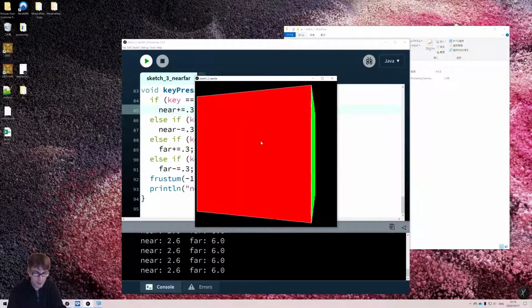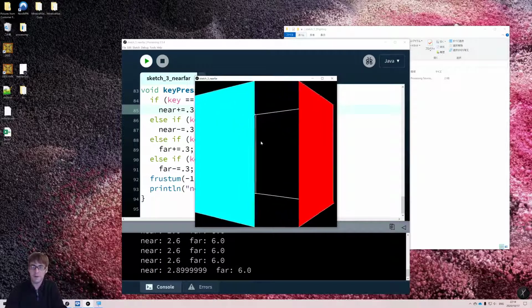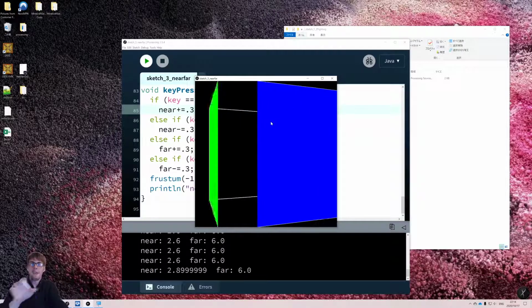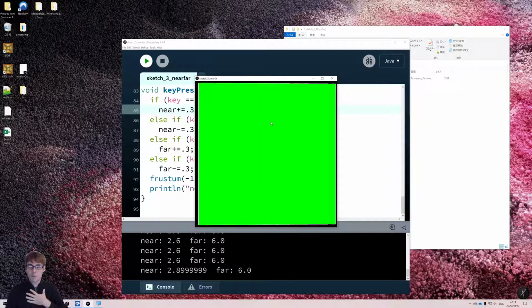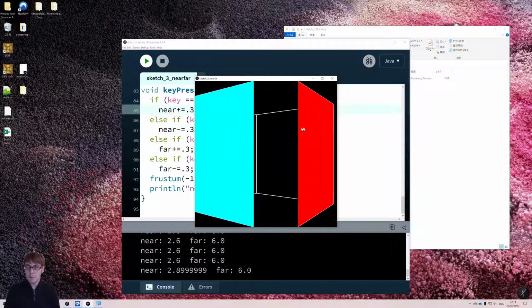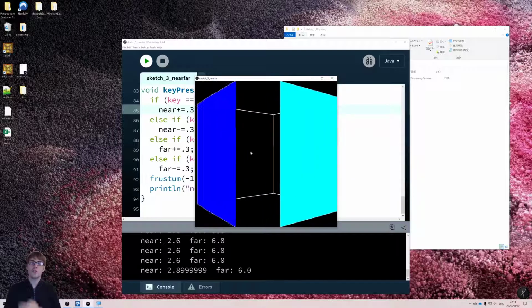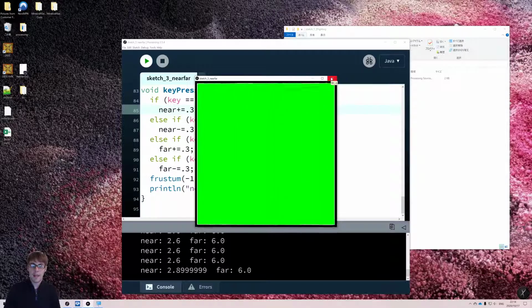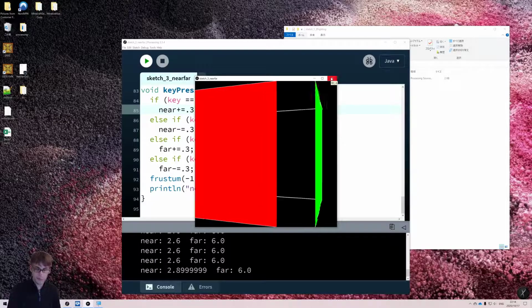Okay, I'm going to move the near plane even closer. There we go. This is what you expect to see. Bam. So what you're doing is, as it hits the near plane, it's just lasering it off, and we're seeing inside the cube. Now, because I have backface culling enabled, you can see that we just see straight through the cube. We just see the wireframe. If I had backface culling not enabled, we'd see the inside of the cube.